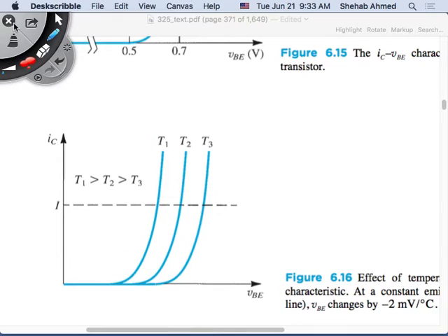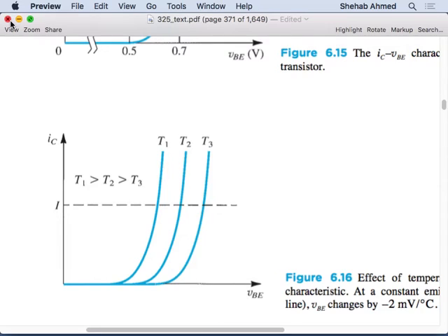If you talk about paralleling devices later, which devices do you want to parallel? Devices with negative temperature coefficient or positive temperature coefficient? Definitely positive temperature coefficient, because if it gets hot, you want it to resist increases in current. And then what will that do? If you resist increases in current, the current will flow through the one that's colder, less hot. Meaning that one will now get hot, its temperature will rise, and it will resist. So at the end of the day, the device currents will balance each other out, because they all want to operate at the same temperature.